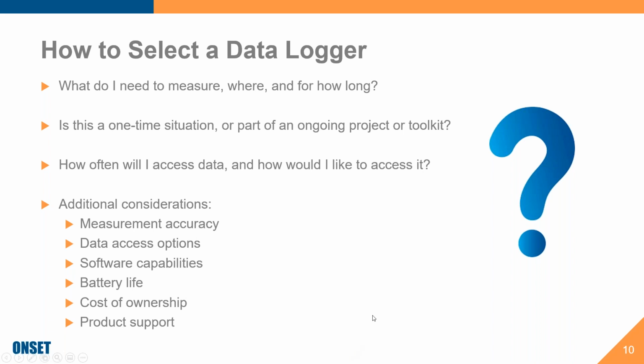Now, how you're going to choose a data logger. The first question I would ask if you were calling us for help is, what do you want to measure? And I'd probably ask you to describe ideally what it is you want to accomplish. What's the goal? Where do you need to place it, and for how long? Some people are doing short-term studies and want to do a quick test. Some are in areas where they don't have easy access, and if you have cellular or Wi-Fi or Ethernet communication, for example, you can access the data that way.